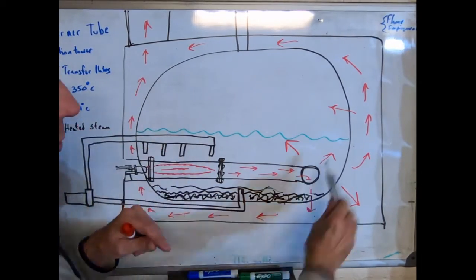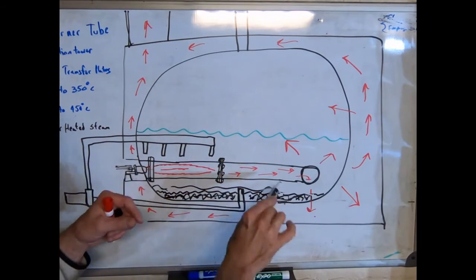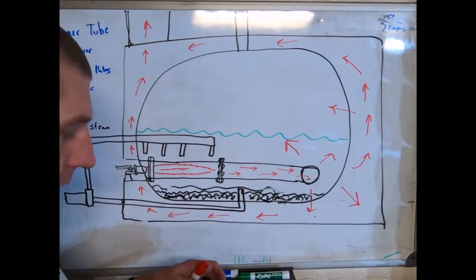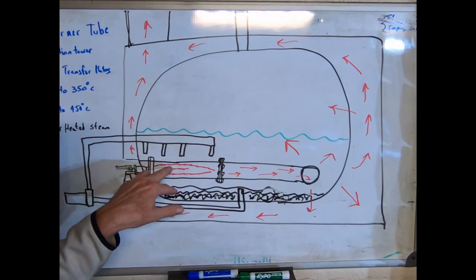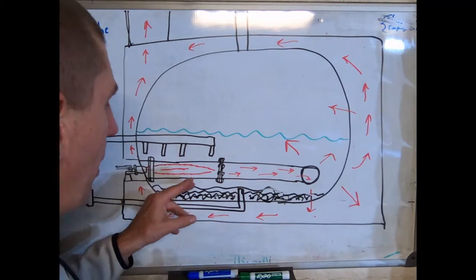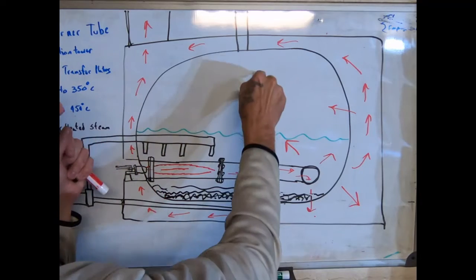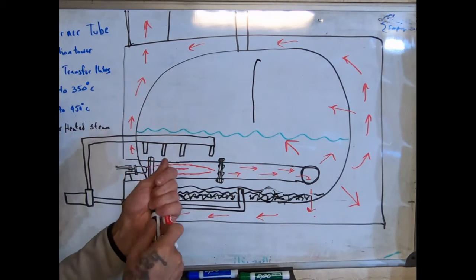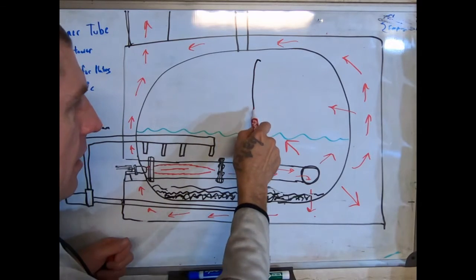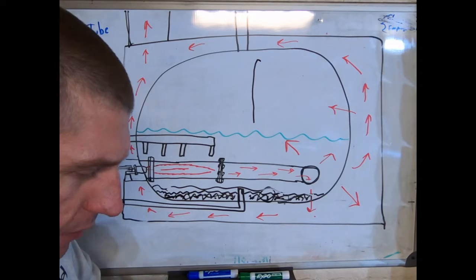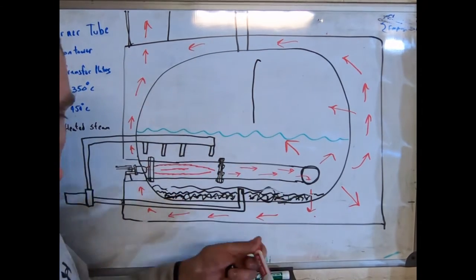So let's talk about flame impingement for a second. When a flame directly hits metal in a boiler system like this, the research that I have done on the subject indicates that a fluxing action takes place with unburnt fuel. Let me draw a small sub-diagram here. You've got a plate of steel here, okay? And one of the things that's protecting it is a small oxide layer on the surface, whether it be rust or whatever. It slows down the speed of this piece of metal just rusting to nothing.